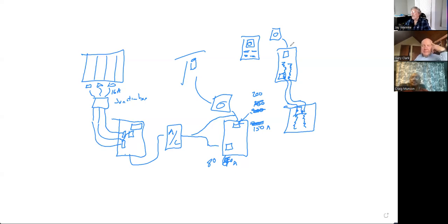But again, if you put another service panel in here, the 120% rule is still going to apply. So don't think that I could put a 200 amp service panel in as a secondary one, and this one's 200 amp, and I've got 200 amps coming in from the utility, and then I say, okay, I want to now connect my system down here. Doesn't it matter? It's only limited by that breaker, I'm still connected to the same limit, right?